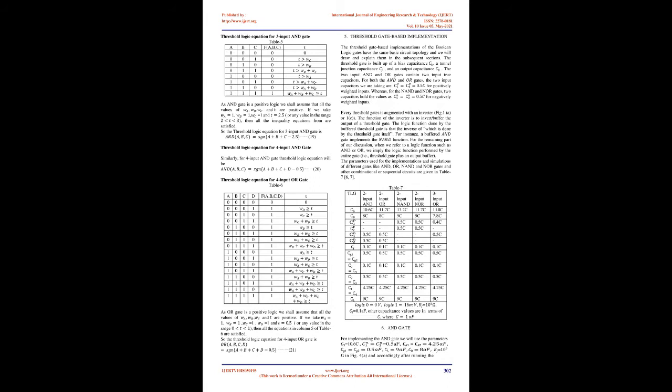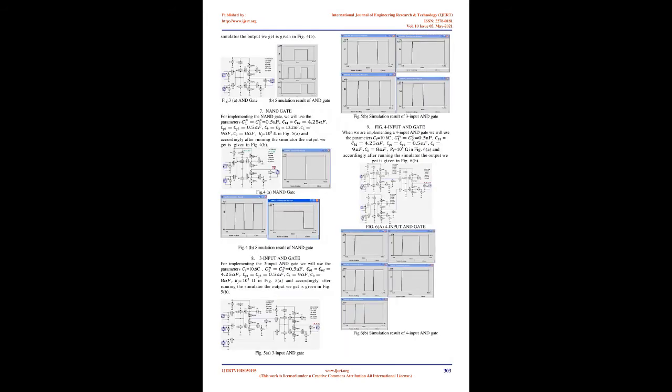To obtain this goal, we set the voltages, V1 equals 0 and V2 equals 16 mV, along with the tuning gate voltages. Both for SET1 and SET2 are applied. When the input is low, SET1 goes in conduction mode and SET2 in Coulomb blockade. This effectively connects the output to the supply voltage and causes the output voltage to become high.